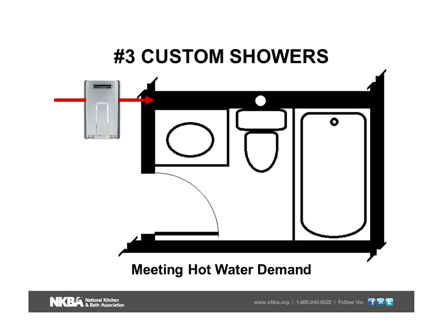Today, a good addition might be to simply put in an on-demand water heater. They, of course, are rated in gallons per minute. So we might think on the surface that we'll simply get one around 3 gallons per minute because, after all, one shower head and the toilet doesn't take any hot water. And what water we're using here, we're certainly not going to use more than 3 gallons per minute.